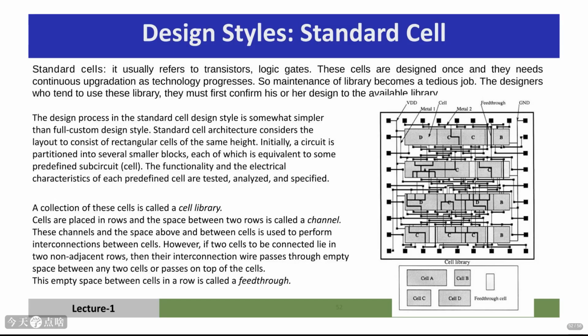Standard cell design is a popular semi-custom approach. It uses a library of pre-designed, reusable cells, typically logic gates like NAND, NOR, AND, OR, and flip-flops. These cells are designed once and characterized for performance. The designer partitions the circuit into blocks that match the available cells. Cells are placed in rows, and the space between rows is used for routing.